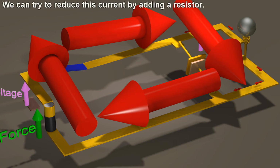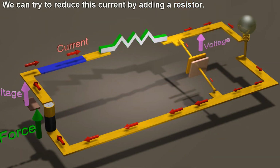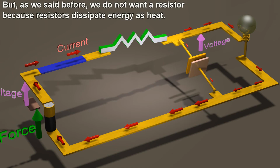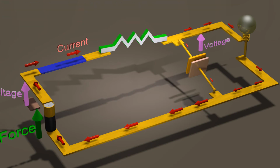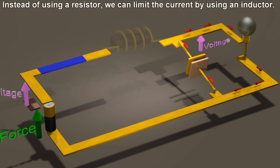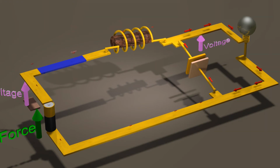We can try to reduce this current by adding a resistor. But, as we said before, we do not want a resistor because resistors dissipate energy as heat. Instead of using a resistor, we can limit the current by using an inductor. An ideal inductor does not dissipate energy as heat.